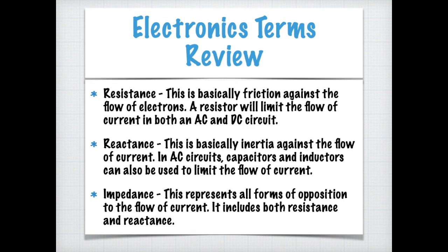Let's start out by reviewing some electronics terms. Resistance is basically friction against the flow of electrons. A resistor limits the flow of current in both AC and DC circuits. Reactance is basically the inertia against the flow of the current. In AC circuits, capacitors and inductors can also be used to limit the flow of current. Impedance represents all forms of opposition to the flow of current. This includes both resistance and reactance.